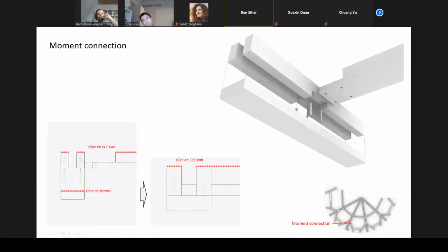In cases at the base of the cantilevers where you've got a moment connection, we continue the bottom flange of the secondary beam all the way through, and then use a few different grouted pins or epoxy pins that are similar to a bolted connection, which can be efficient with timber.